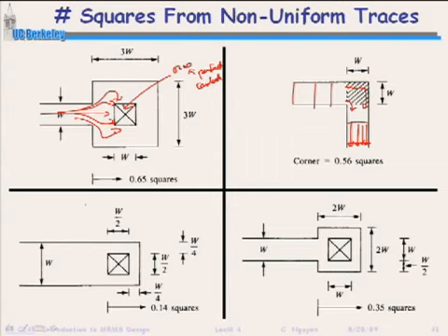Now, with this conductor, the current doesn't take that path, right? Some of the current takes an even longer path that does that, but some of the current takes a much shorter path that does that, right? And because of that, this is no longer one square. And so how do you work these problems? Well, you kind of divide them into more squares, right?